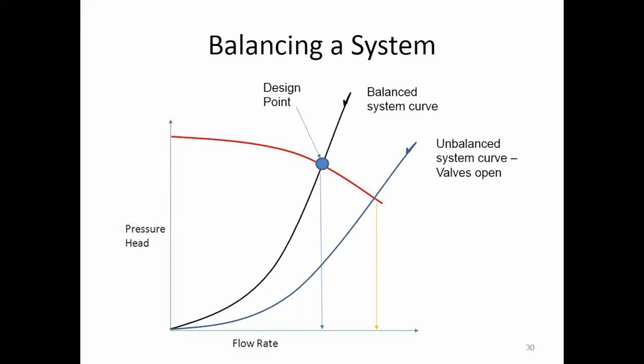So one of the things that has to happen is every project has to be properly balanced. I have seen projects that have not performed well, and amazingly enough, all the balancing valves were open. Once they brought the balancing valves to their proper position, all of a sudden they started to see much better performance out of the system. So it does play a major factor.